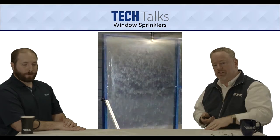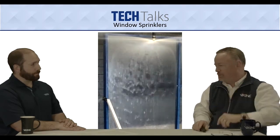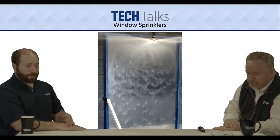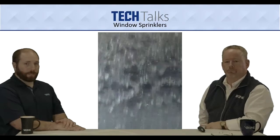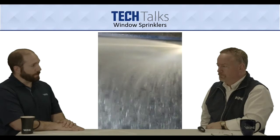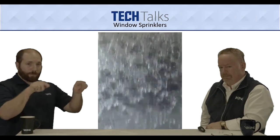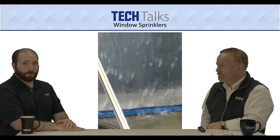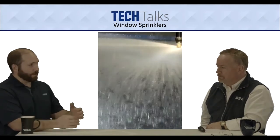So let's look at this spray pattern. Tell us what the window sprinkler is, what's unique about this, and what they're seeing in this spray pattern. Yep. This is a spray pattern that we've flowed in our flow lab. As you can notice, we're getting a nice even sheathing, or coverage, of water over the entire surface of the glass. Basically, it's there to cool the surface. It's going to cover completely from top to bottom so that there are no dry spots. That's what I mean by that even sheathing of water. And that eliminates those dry spots where fire could potentially crack or spread the glass.